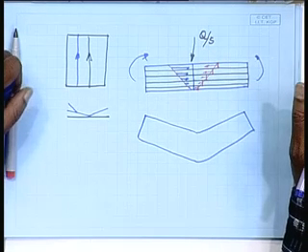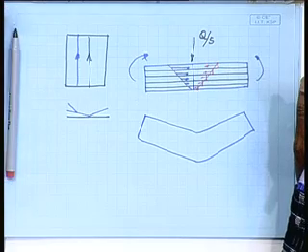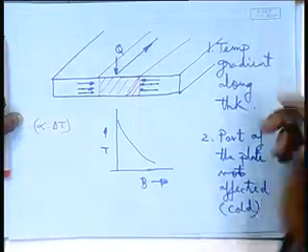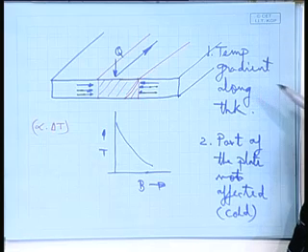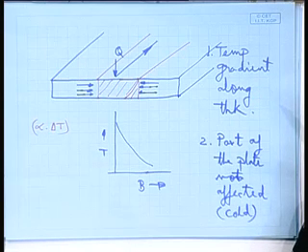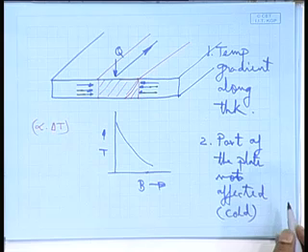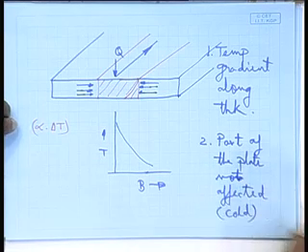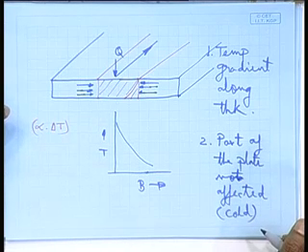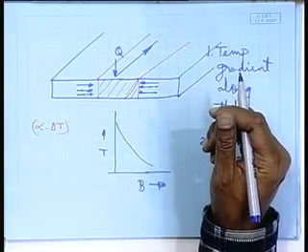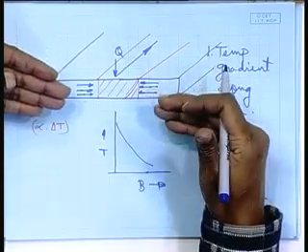When you heat it, it bends, because we will have to achieve these two conditions. That means there should be a temperature gradient along the thickness, which automatically forms, and also part of the plate should not get affected by the heat, that means should remain cold, should give that so-called clamping effect. Then only the compressive stresses will develop, right.